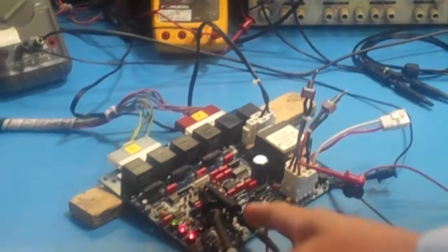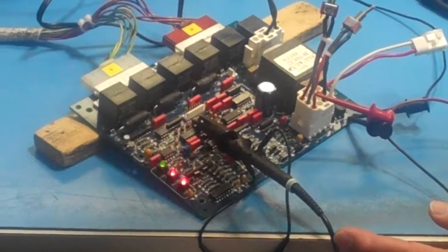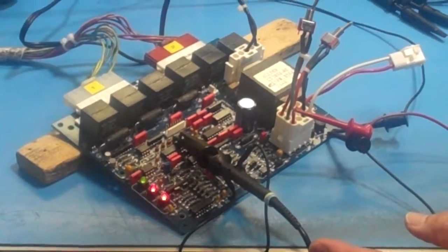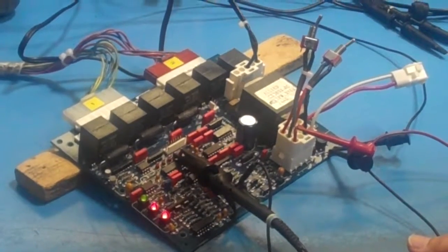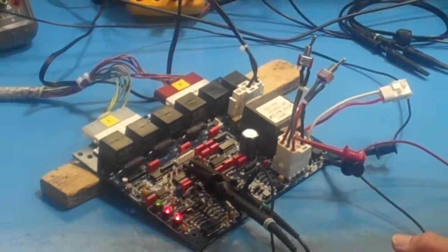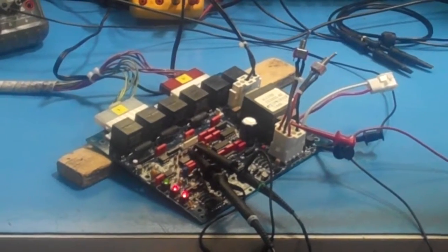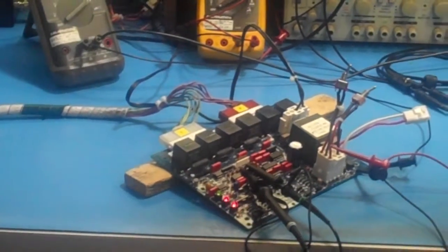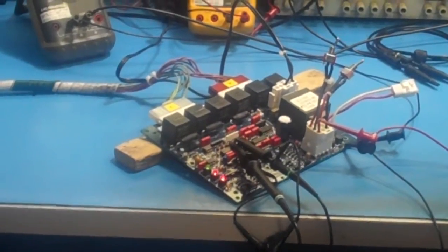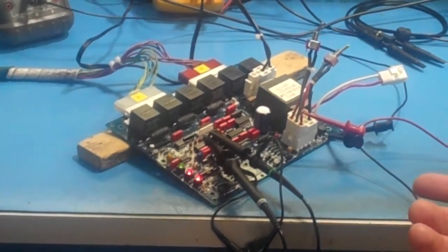What we should have is the 3 LEDs solid, and this is again part of the problem that we have, because the reported failure is that you have LEDs that are flickering. That is a problem associated to the board, and that problem will stay whether the board is configured as an AC controller or as a DC rectifier. So we will have to go back and take a look at that. But the board has to have 3 solid LEDs, and that's what we have right here.